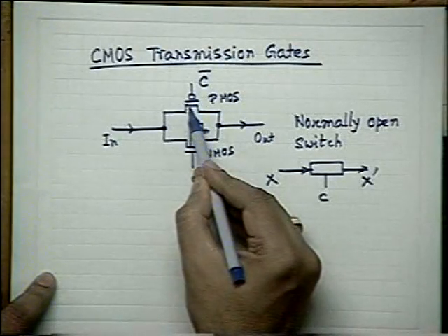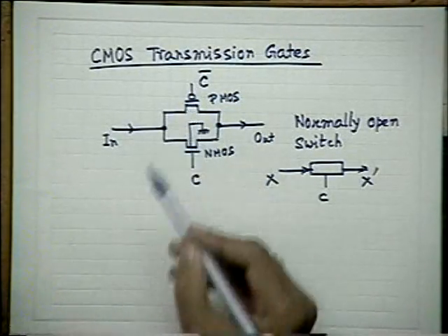And the PMOS, usually in the case of PMOS, the NWell cannot be kept grounded, isn't it? NWell is all floating. So what is done? One end of the NWell and one of the two P plus diffusions, either source or drain, whatever you call it, is connected with that NWell tub. It is not grounded. That's the only difference, with what I told you, that MOSFET is a bilaterally symmetric device,